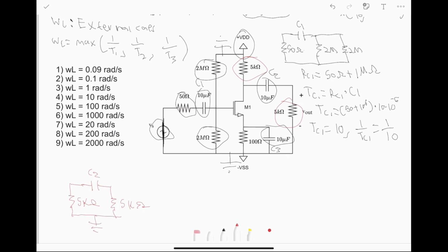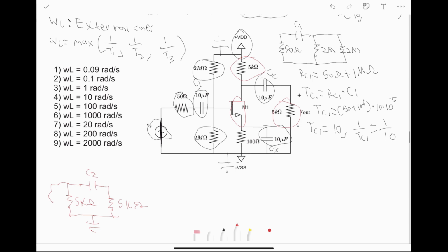You might ask why we can ignore this MOSFET right here, because there technically is this dependent source also as part of the circuit, but we've shorted the AC source and the DC sources, so we know that the voltage associated with this dependent source is going to be 0, because remember, the current flowing through here is VGS times GM, but we know VG and VS are 0, so this dependent source is off.